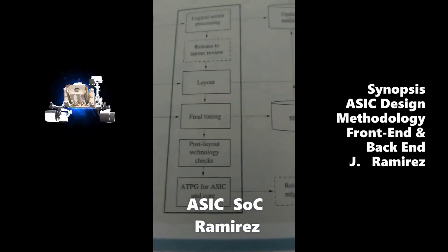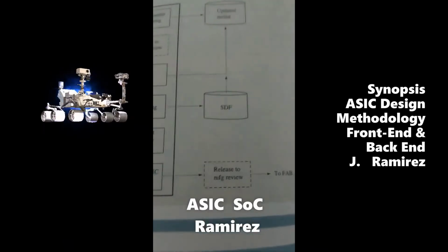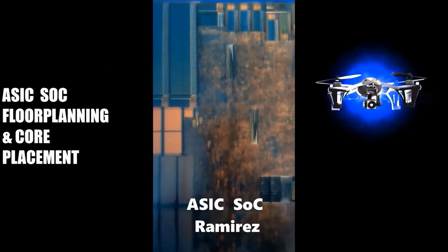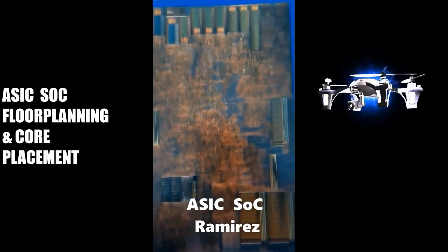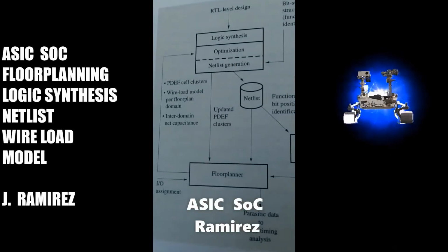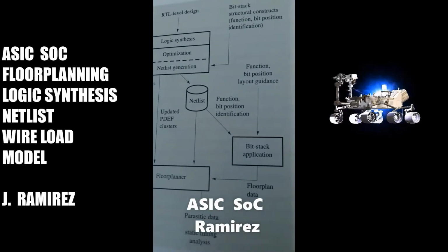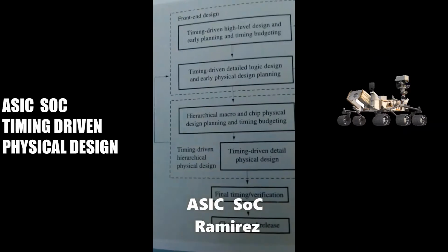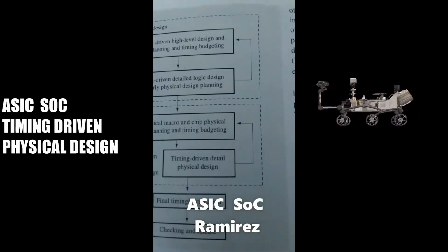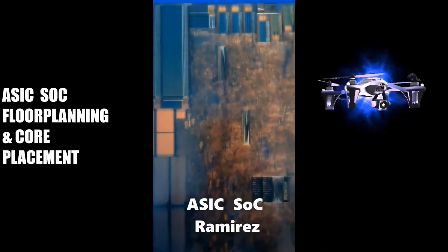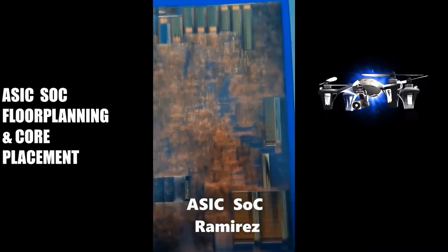The area estimation function described determines the appropriate width and height of each macro cell in the hierarchy, based on the wire demand in the X and Y directions, as well as for any child cells or other descendants down the hierarchy that have rigid shapes, in order to fit each macro cell and its sibling macro cells into the parent macro cell in an effective way.